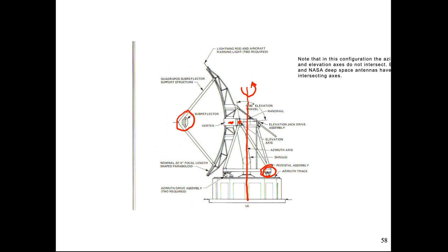Okay? It's essential that the track is plane, is along the local vertical. At Madrid there was one antenna, due to poor geological studies of the soil, which started tilting a little bit, which made pointing very difficult. So what they decided to do is to dismount the antenna and rebuild it 100 meters away, where the soil was more stable.